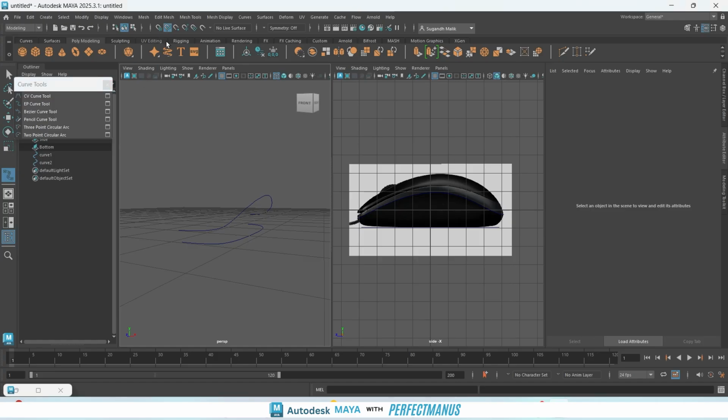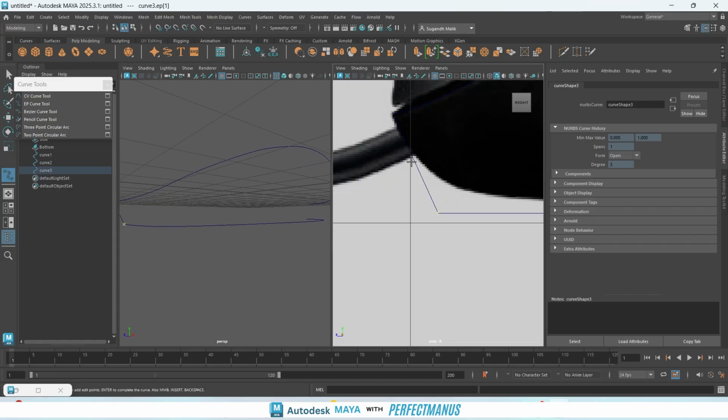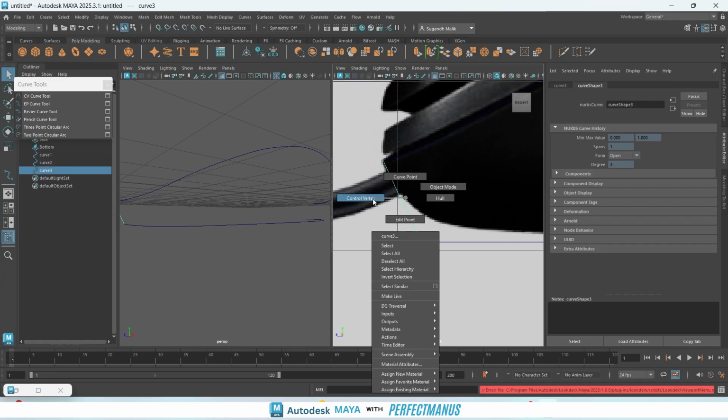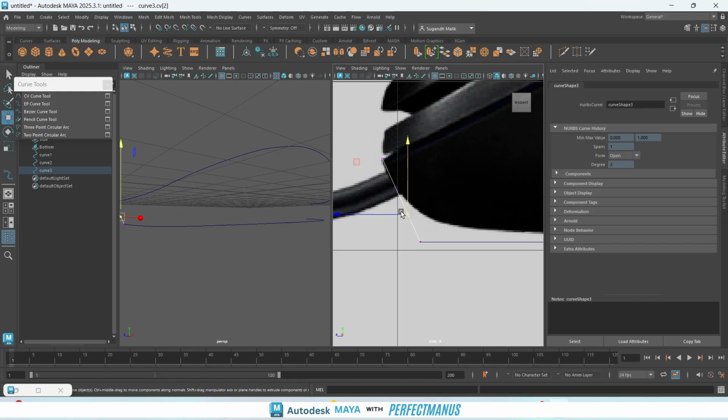By clicking on this one, attach to curves is enabled. Now you need to keep pressing C while you click on this rail. See, by going to the edges you can leave it, and again, holding C and click, these get selected. Here we can see these ones as it has some value. By pressing Q and going to the control vertex, you can move them to create a little bit of a curve. Okay, the kind of mouth that gets created.